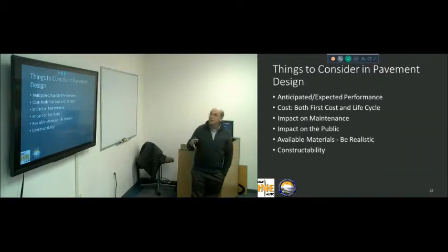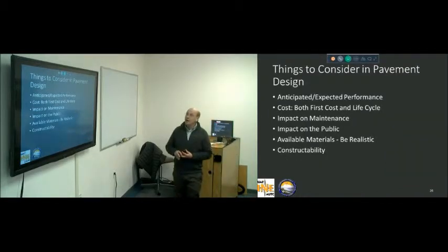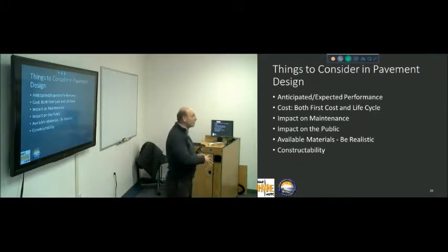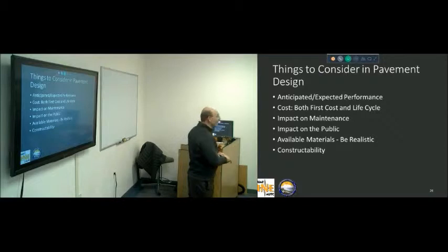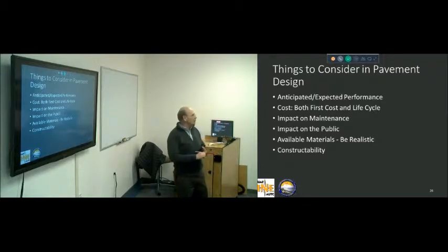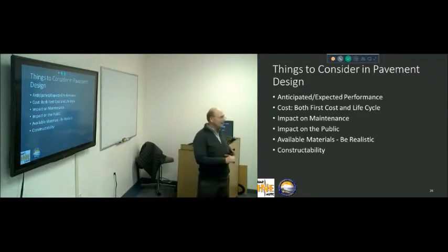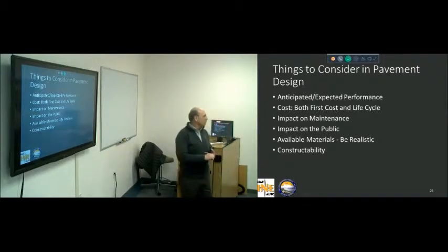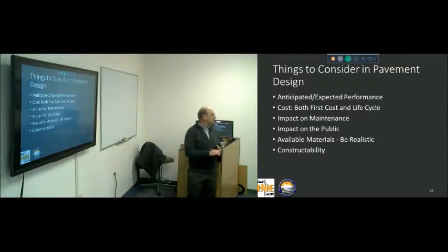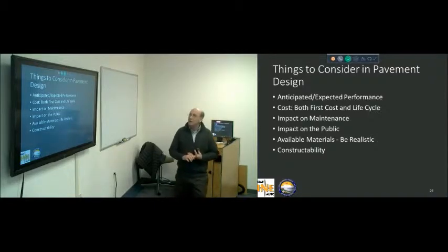Okay. Some of the things we need to consider in our pavement design: we need to understand our anticipated and expected performance. What do we expect out of that pavement? We need to define that in our own minds. Are we going to limit the rutting to 1/2 inch or 1/4 inch? Are we going to have 20% cracking in 10 years, or 0% cracking in 10 years and something else in 20 years? What are we expecting out of that?